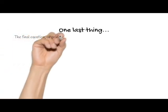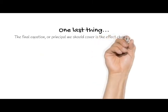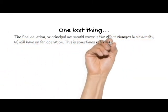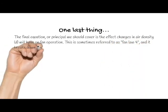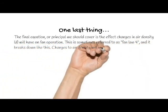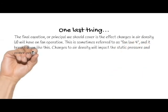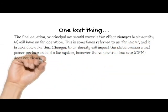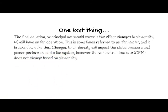Okay, one last thing. The final equation or principle we should cover is the effect changes in air density will have on fan operation. This is sometimes referred to as fan law 4, and it breaks down like this. Changes in air density will impact static pressure and power performance of a fan system. However, the volumetric flow rate, CFM, does not change based on air density.